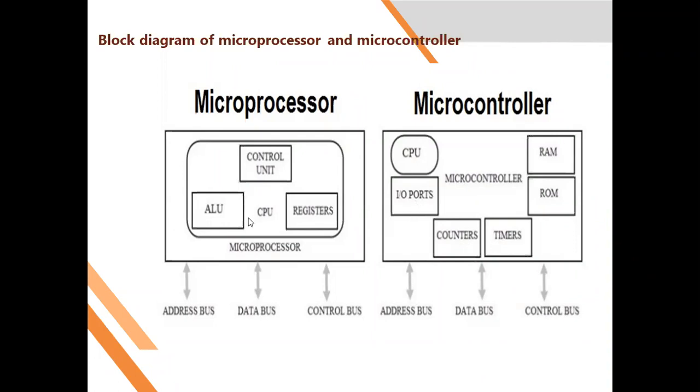Now see here, that is not the case available in the CPU. So to give the data and to take the data, there is not a single pin available in the CPU. So how can we give the data in a microprocessor? We have to use another IC, that is 8255. Whenever we want to connect any peripheral devices to take the data from the system or to give the data to the system, we have to use a separate IC 8255. Actually that is not part of your syllabus, but when you elaborate the microprocessor interfacing, then firstly you have to study that IC also.